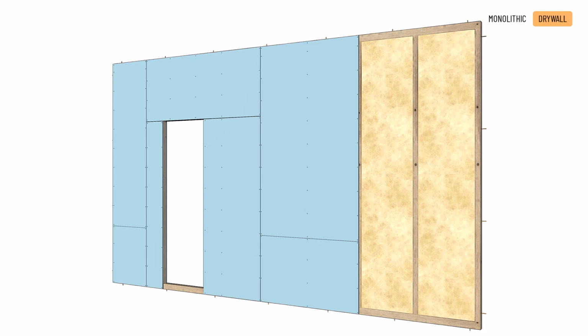Another advantage is that, due to their low dead weight, they do not require slab reinforcement in the form of beams or ribs. The space between the studs allows for the installation of tailor-made thermal and acoustic insulation, typically in the form of fibre thermal insulation. The structure's thickness can be increased as desired to meet special requirements, including fire resistance, with the right design. The panels mounted on the stud wall, mostly gypsum board, can be placed with great precision. These drywall partition walls do not need to be plastered, but can be painted immediately after applying wall putty.